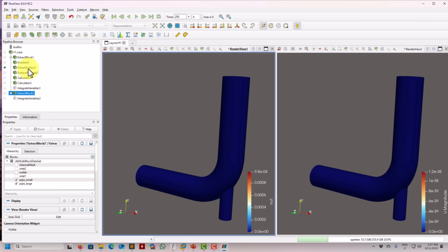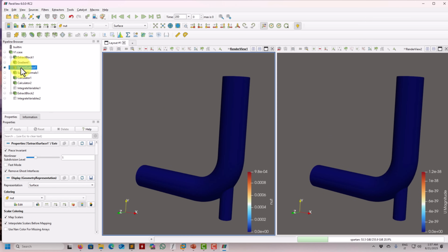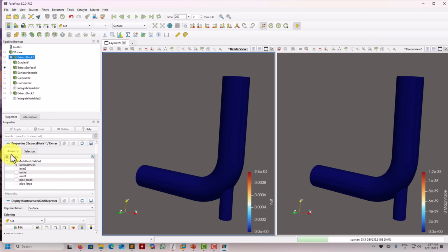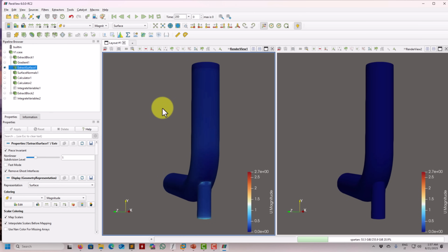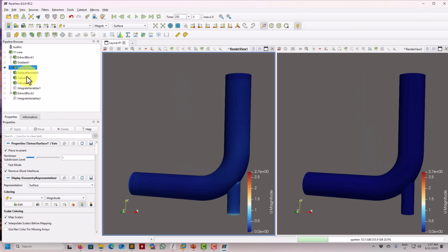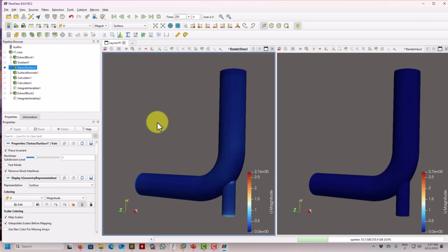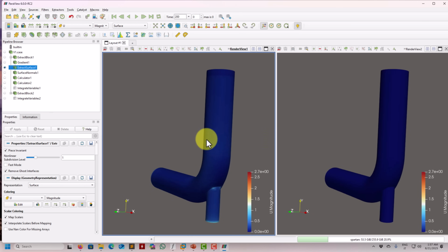However, when I do this extract block on my whole internal mesh and plot here, you have the velocity. So very important steps to project the velocity, and to this matter also gradients and so on at the walls. This is the extract surfaces step, and you can confirm that the fields are exactly the same. Nothing changed, just a projection.